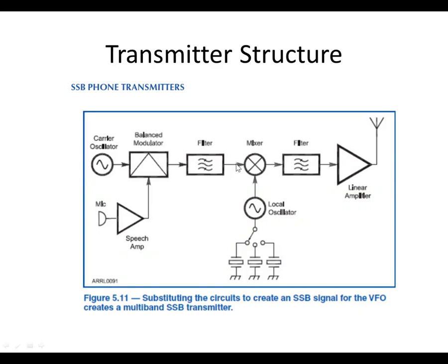And then that goes into a mixer where there are different oscillators. In this case, these are crystals that you would change, using different crystals to get different transmission frequencies. It's pretty common in the older legacy equipment. This is probably done more electronically now than with the crystals. So you take that oscillator, get your mixer to multiply it together. That's what is called heterodyning.